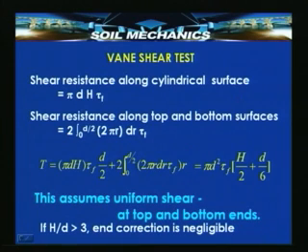Why do we consider a cylindrical surface? It is very easy to imagine. As the torque is applied and the vane rotates, it cuts a cylindrical surface through the soil, and therefore the shear resistance of the soil is mobilized along this cylindrical surface.